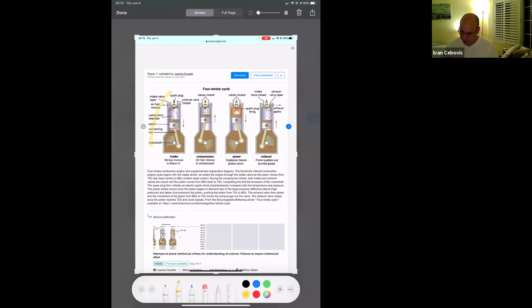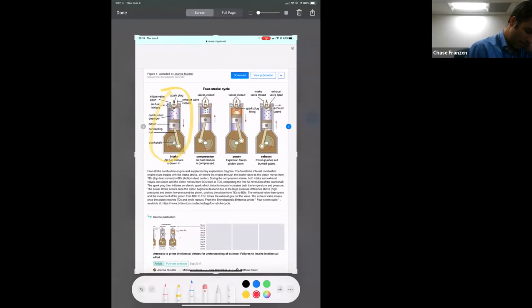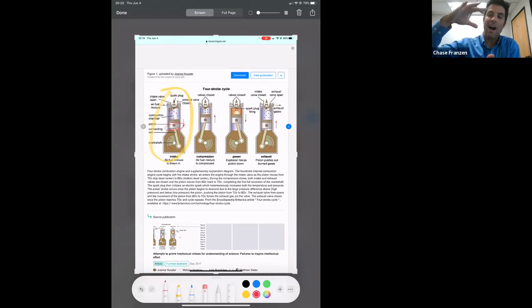so if I've got a piston here, the idea is that you've got this plunger right here where I'm circling in red, and you've got this arm, this connecting rod that is connected to the crankshaft that's spinning. And these pistons are all interconnected in the 4 cylinders. So as one piston is coming down and making a bigger space, the next connecting rod is pushing the piston up and is making a smaller space inside of the cylinder.